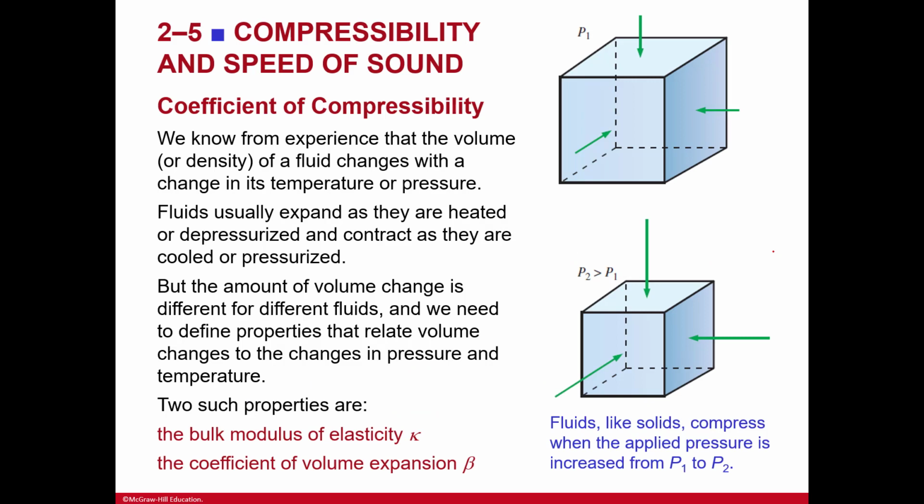So here we've got compressibility and speed of sound. So, coefficient of compressibility, okay? We know from experience that the volume or density of a fluid changes with a change in its temperature or pressure. Fluids usually expand as they are heated or depressurized and contract as they are cooled or pressurized. But the amount of volume change is different for different fluids.